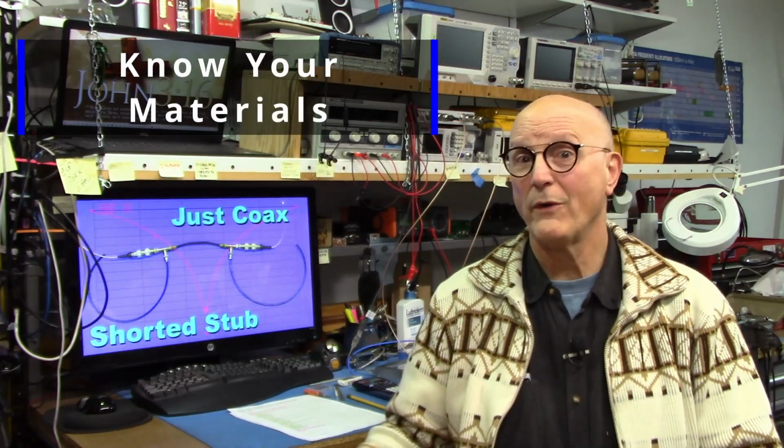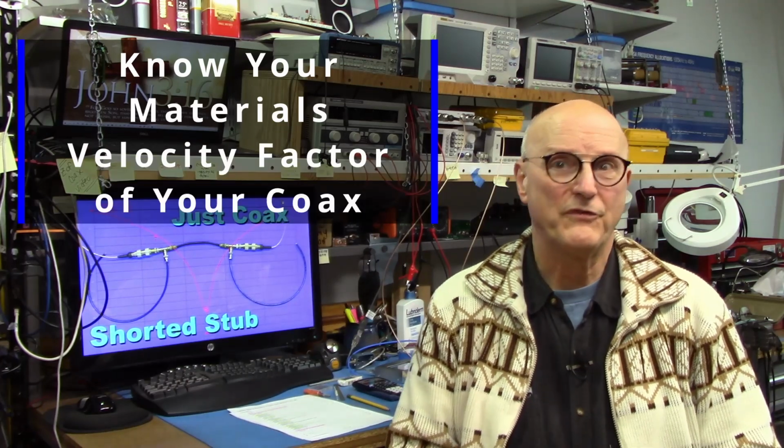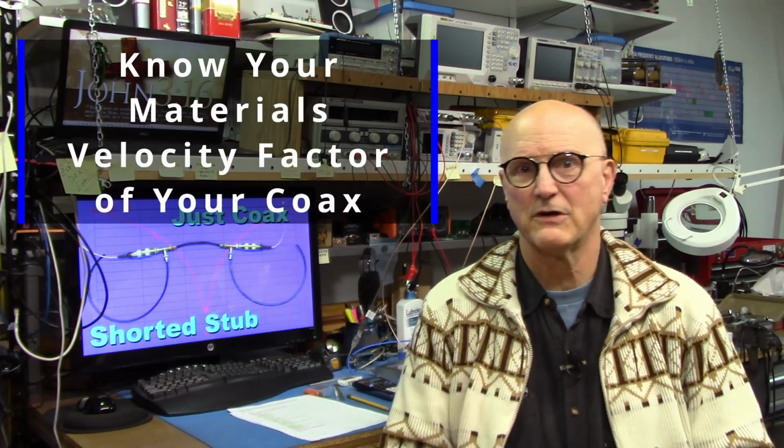Now that we have an idea how it works, how do you design one of them? Designing one of these begins with knowing your materials, specifically the velocity factor of your coax that you're going to use. No matter what you do, you must know the velocity factor of your coax if you're going to do this. Now you can find this on the data sheet for a specific coax that you plan on using, or you can measure it for yourself using one of several methods.